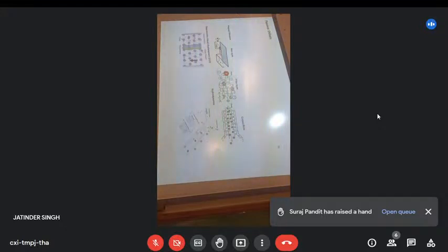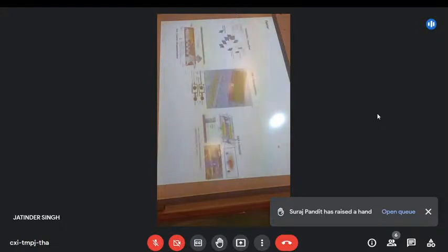Hydrodynamic effects we already talked about when we had the obstacles and the big particles get stuck, whereas the smaller particles can just continue down into the channel. And we can also combine different forces at the same time. So here we've got the Dean flow of going around the corner, and at the same time we can impose on our sample so it's focused in a flow like that. We can then do some focusing as well by just sandwiching that flow vertically so that we can get a sheath of our inlet. So we first get it all concentrated and then we push it up and down.